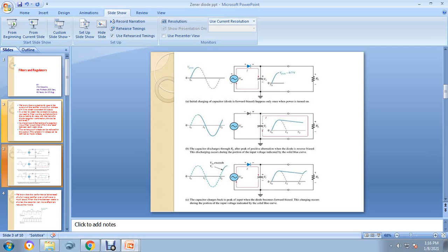Here I have used one diode and the load resistor at the beginning of your rectifier. Now I will use one more component, a capacitor at the output. We have two types of filters, capacitor filter and inductor filter, but instead of going for the inductor filter, most of us use the capacitor filter only, as it is more efficient compared to the inductor filter.